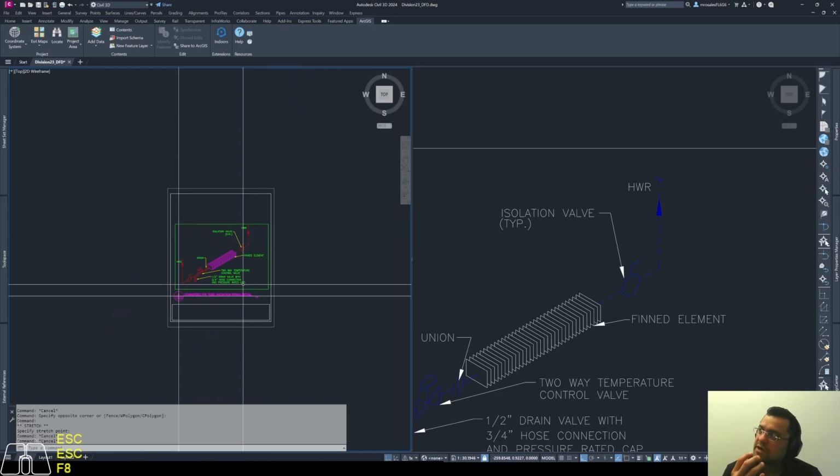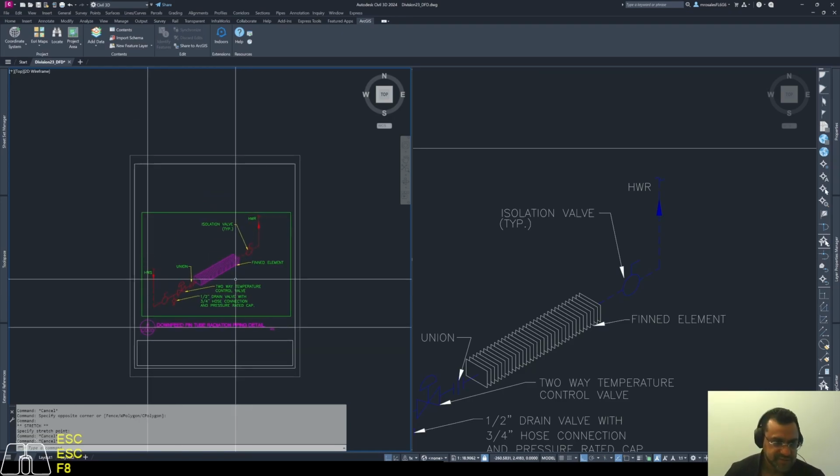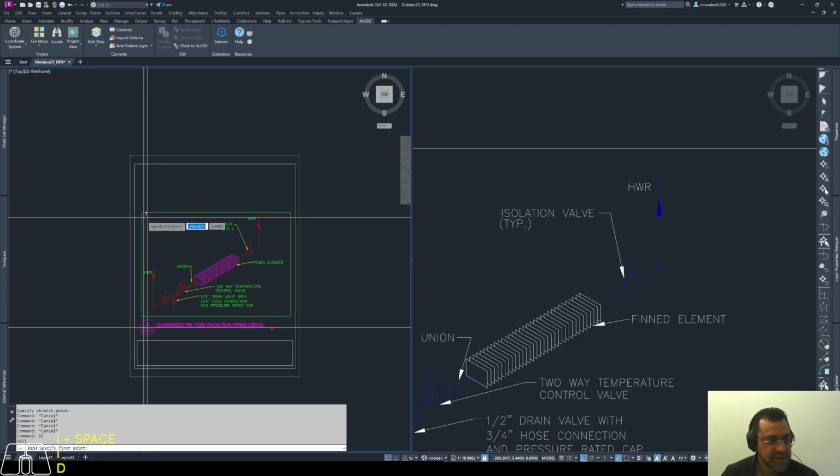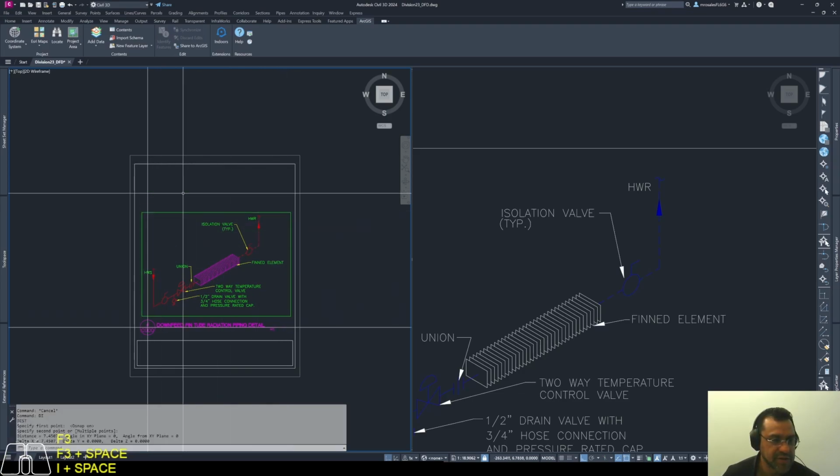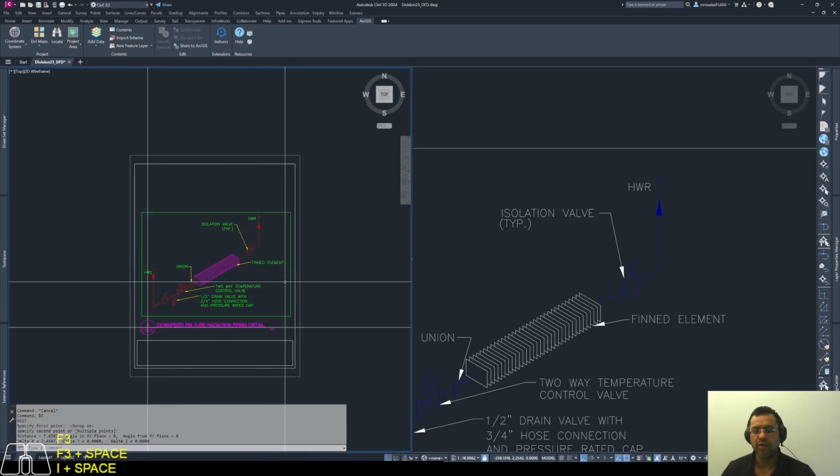Remember, right now, the way that we talk about putting together the details is in the model space, and we will have to place them just to modify them and apply some properties. So we copy and paste them in paper space. That's the way that we should be working. If I measure this distance from here to here, it's almost 7.5 inches.